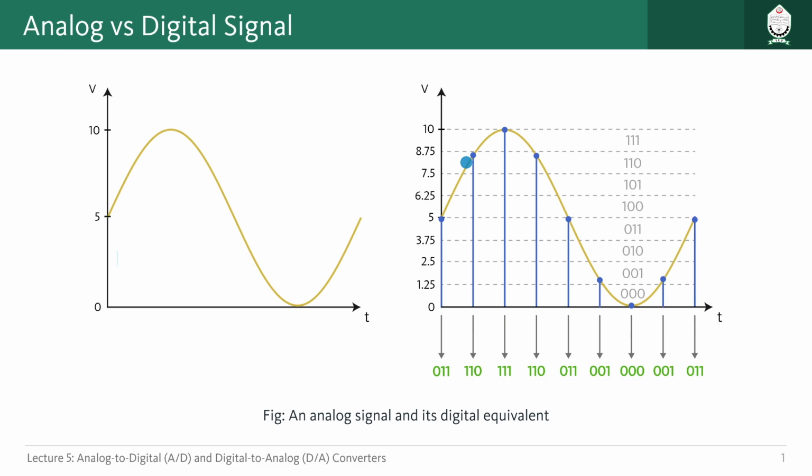Each of the signals we have in the sampled signal will obviously fall within one of the states we have here. So instead of this continuous value, we have only 8 possible values for amplitude now. This is called quantization. Then, because our digital systems only understand 2 possible states, 1 and 0, or you can say 5 volt or 0 volt, we will convert or encode those quantized values into a digital value, a binary value, right?